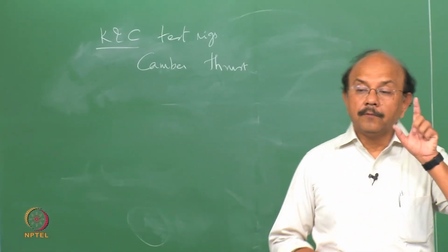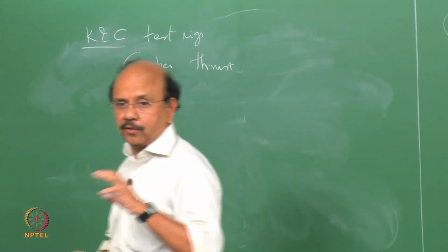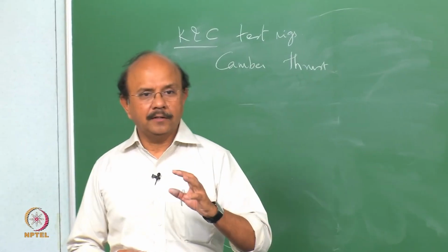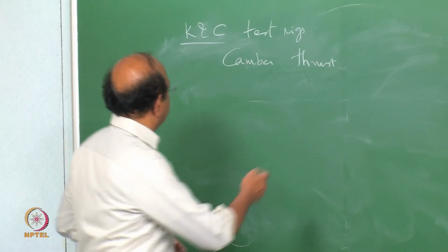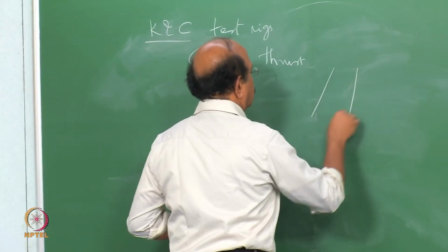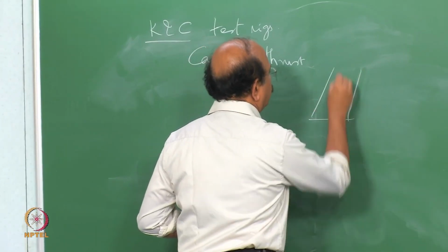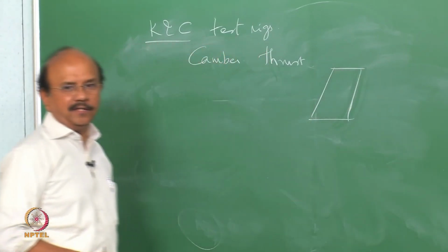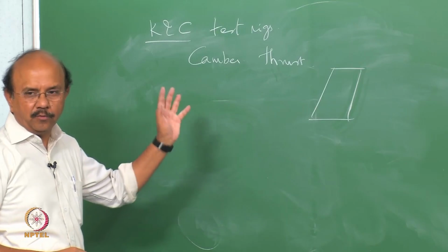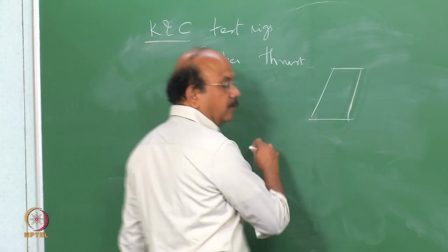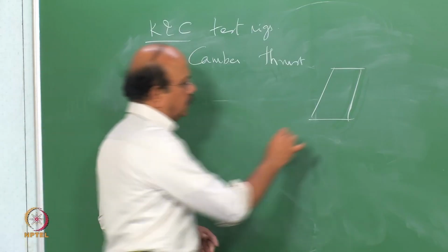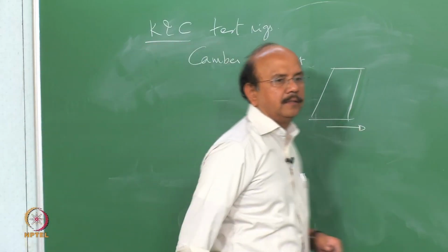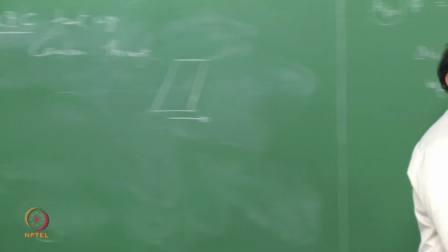Right? Remember that this was due to the deformation of the tire. Because when you roll a tire with camber, that introduced camber thrust. In other words, if this were to be the camber, I'm just exaggerating it, cambers are very close to 0 in most of the modern cars, close to about 0.5 to 0.75 in many of the trucks. So that would result in a force F.